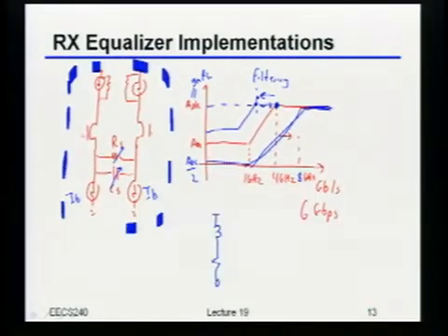Okay, now, the bad news is, usually if you actually wanted to do this, the inductance you'd have to use would be ginormous. Okay, especially if you have a small cap. So, usually you're not going to actually be able to do that. Even though actually, if you could use an inductor, there's some advantages you could get from doing that. So instead, what you actually end up having to do is build what's called an active inductor. Okay?